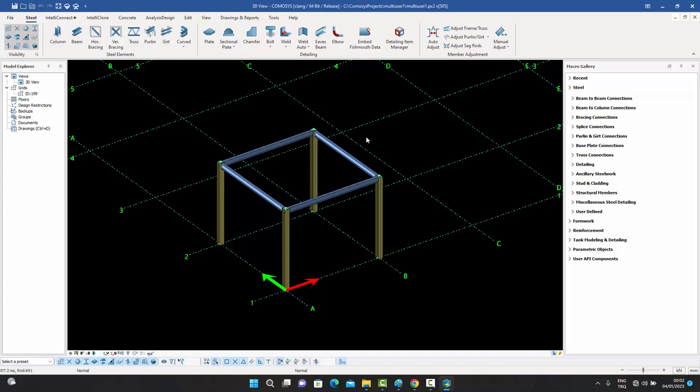The admin will create the database. First of all, you will need to set up the multi-user server. The admin will create the database, create the users, and send the registration file to the users. The users will then go to the multi-users tab, create their own passwords and log themselves in. The owners can decide to create new projects and put them on the server.